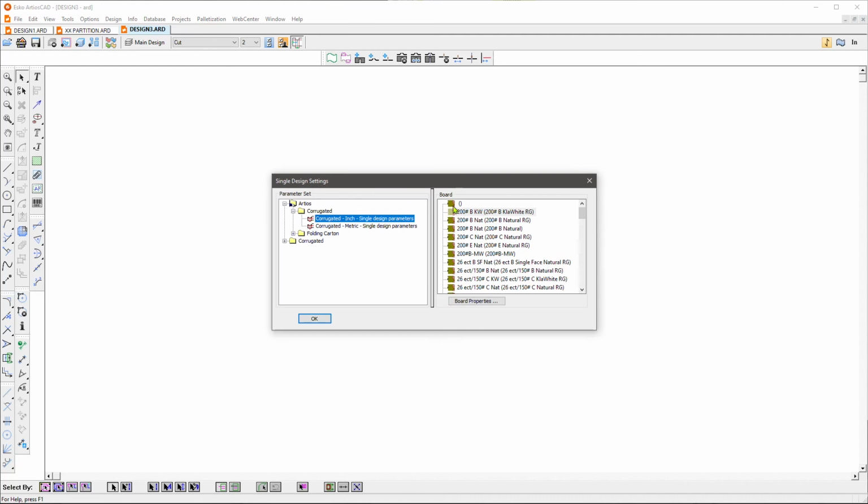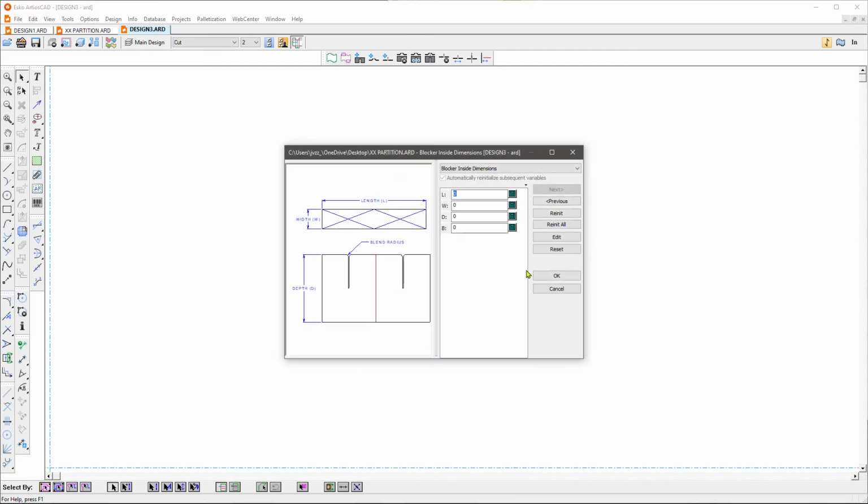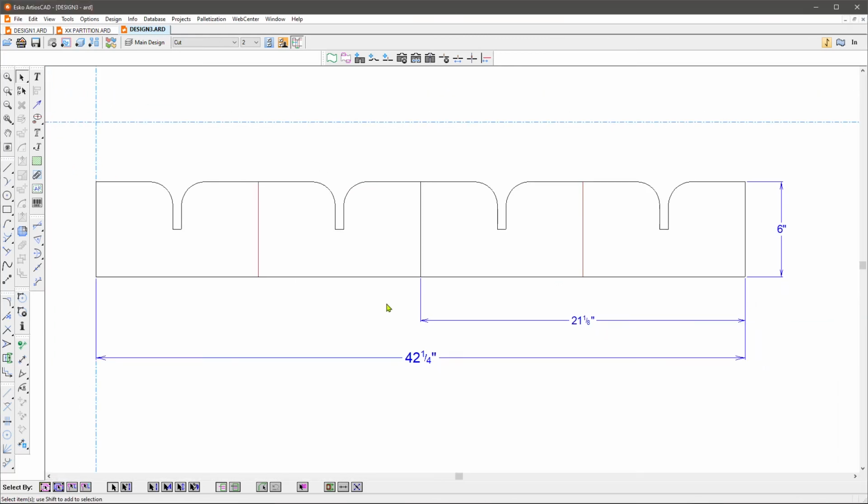It gives me the preview and everything. I can select, let's do C. And let's do 16 by 8 by 6, do 1.5. Boom, there we go. Of course, it's going to be up to the designer to make sure that their radius isn't inappropriate for the depth. I could put a check condition in there.